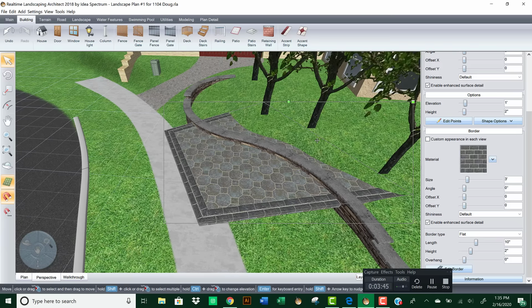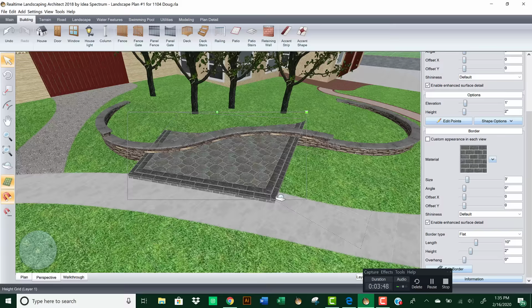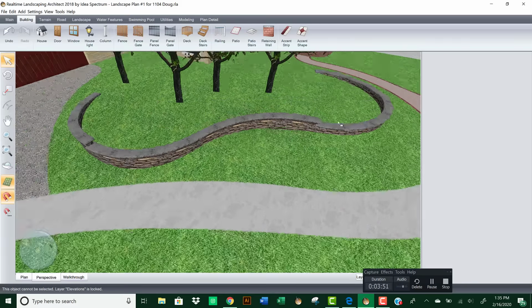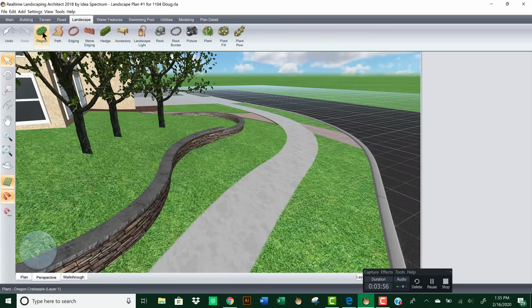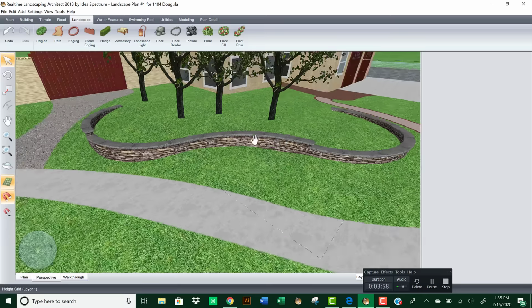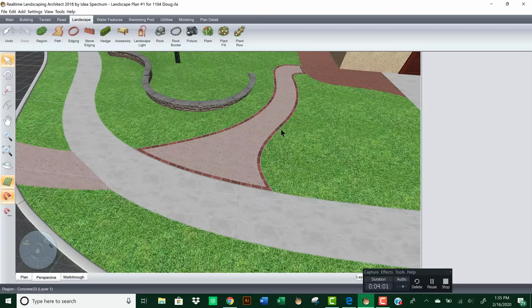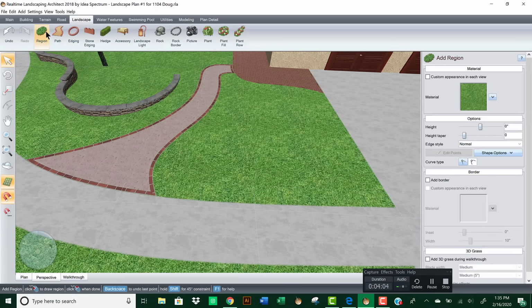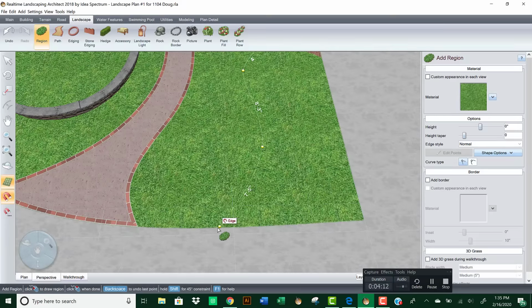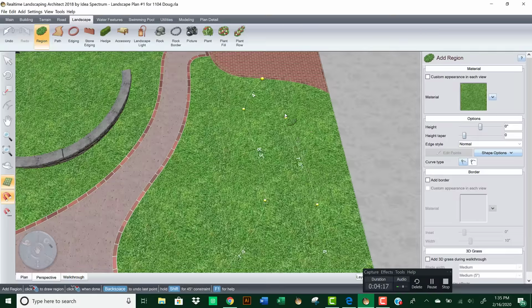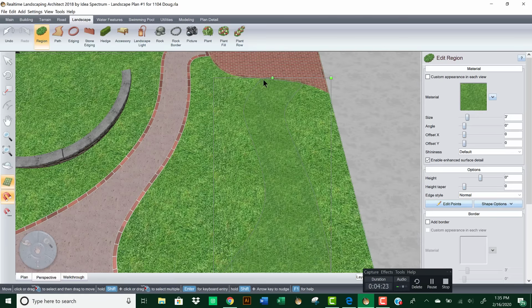If I make it so it's above the sidewalk over here, it's just a nightmare. So if I want something to follow the grade of that slope, I go into landscape and create a region or a path, either one. This one was a region that I did, so we just go region, and I drop in some points. I'll do point, point, and make it mimic a neat little shape. That way you can see I'll mimic the shape of this patio, and we can go from there.